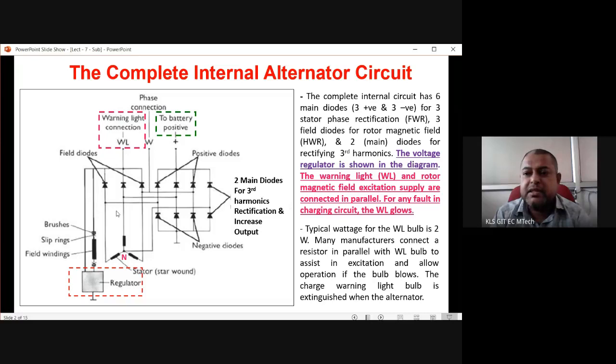So the alternator is the three-phase generator, which is mainly used for generating all the power required inside the vehicle. The engine rotation is given to this three-phase alternator, and the stator can be delta connected or star connected. Here it is star connected, and from this star connected stator we are taking out four wires. These three wires are for the RYB phases, so they are rectified here, and the rectified DC is going to the battery and to other electrical needs of the vehicle.